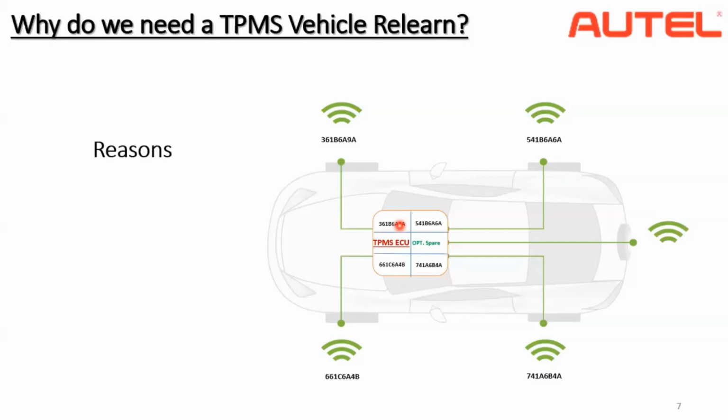Right, so for continuity of the information, what we're trying to achieve is that each vehicle has a unique sensor ID, as I've told you, at each location. And the reason for that is, when two vehicles are going down the road next to each other, both having a TPMS feature, one car should not pick up the TPMS signal from the other vehicle's TPMS transmission. So that's our goal here. That's why we program it uniquely. Each sensor should be programmed uniquely with different codes.